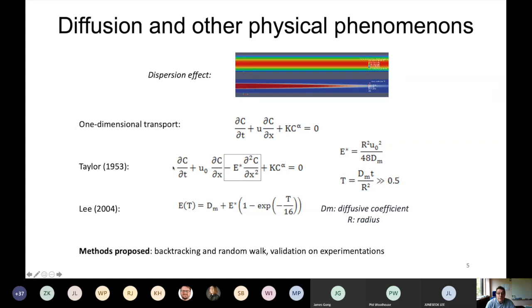So here, 2D or 3D is replaced by a 1D equation, and there is that apparent diffusion, which is called the hydraulic dispersion here. So it is possible to solve that equation with the right U, which should be transient as well, and that kind of term for the dispersion and the molecular diffusion as well.